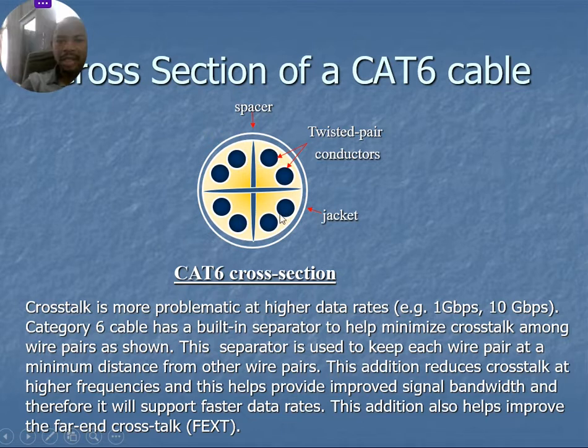So they are adjacent, and that will create crosstalk on this end, because voltage will be induced. As current flows in this wire, a field is generated, and this field induces voltage on the other side, and every voltage that is induced here as a result of the electromagnetic field causes what we call the crosstalk on this other side.